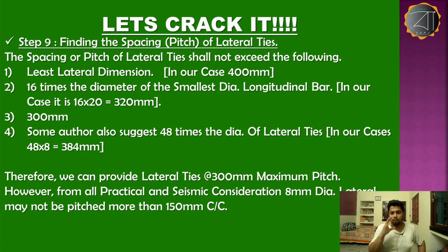So, it will be minimum if we multiply with the smaller dia bar instead of the larger dia bar, right. And in the diameter of the lateral ties, the criteria was to find the maximum diameter, right. So, it is obvious that we have to work with the maximum dia bar. That is how the concept lies.